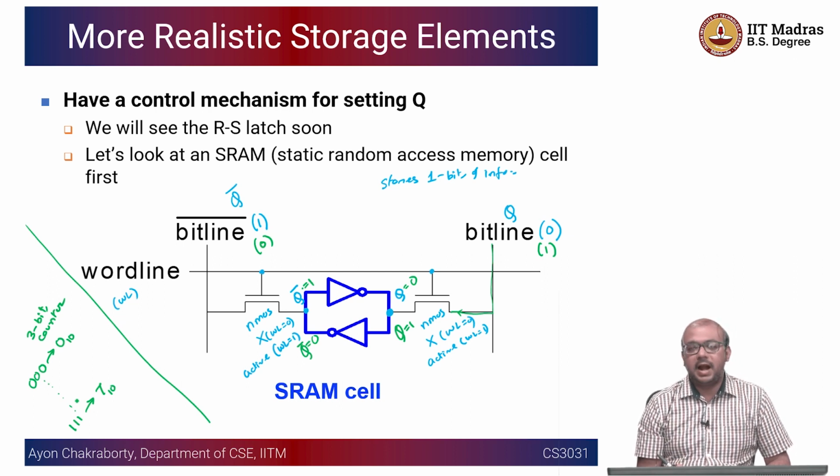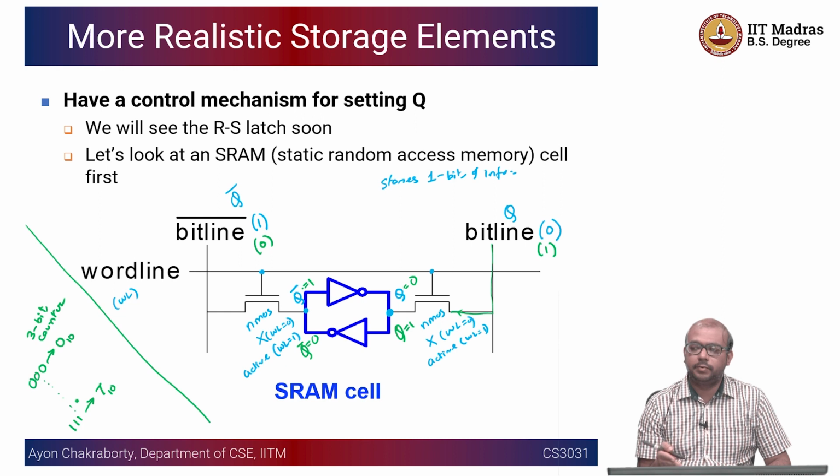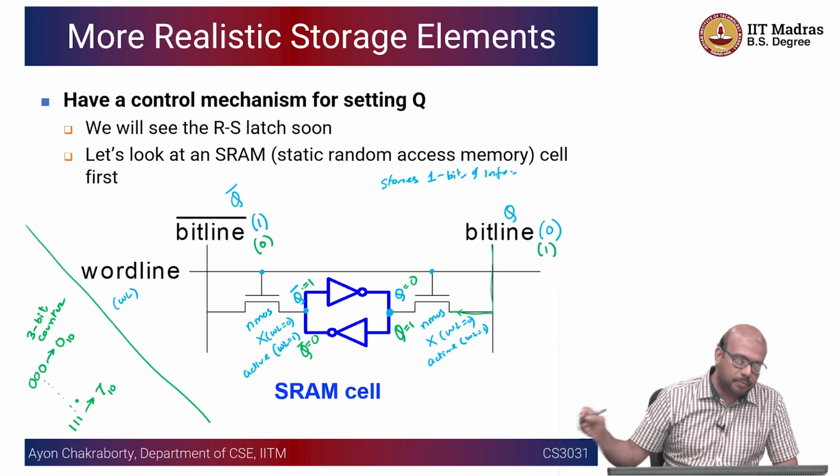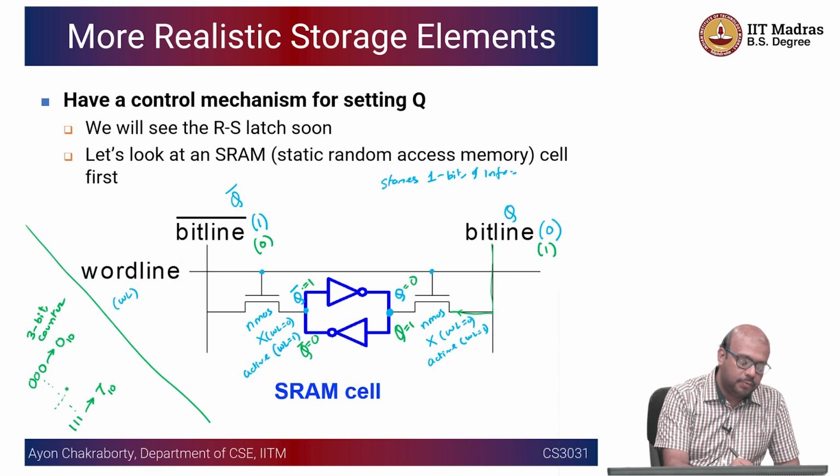Okay. For an adder, that is not the case. If for an adder, if you ask me that what is the current output of the adder, I will ask you that please tell me your current inputs. Okay. Whereas for the counter, I have to tell you what was the previous output. Okay. So let's say at a certain point in time, you have an output of let's say 4, right? 4 is 100.